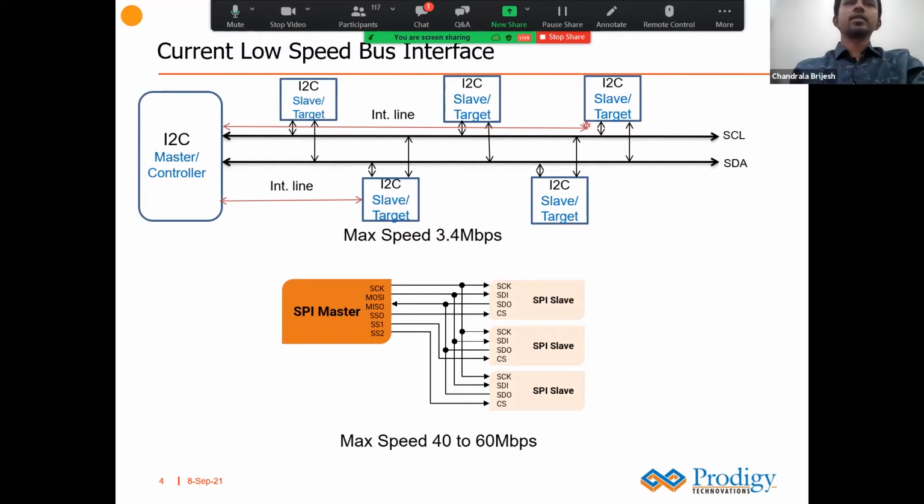Thank you, Godfrey. So first, let's talk about I2C and SPI. What were the drawbacks of those, why did MIPI come up with I3C, and what are the advantages of that? In I2C there are a clock and data line, but for interrupt an additional line is required. So at the system level, you need to have multiple IOs, and that becomes a little bit complicated.